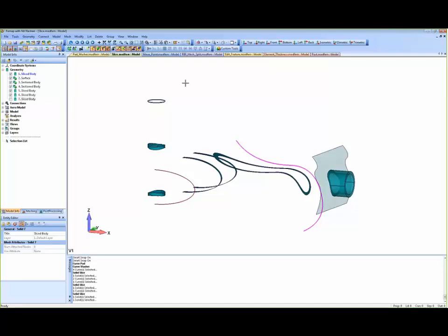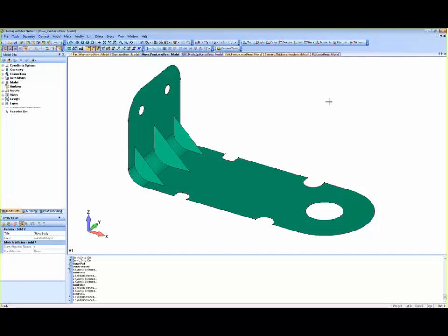All right. Now, as I alluded to just a few moments ago, in Femap 11.2, you also have the ability to move points that are connected to solids or surfaces or curves. In previous versions, if you tried to move some points, it would say can't do it because it's attached to a solid. Now, in Femap 11.2, you can do that.